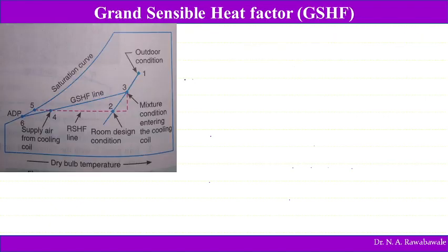So now we will see the grand sensible heat factor. This grand sensible heat factor is defined as the ratio of total sensible heat to the grand total heat, which the cooling coil or conditioning apparatus is required to handle.